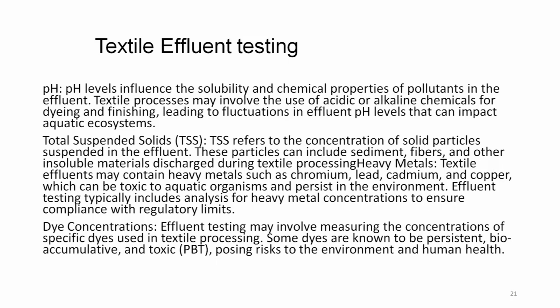pH levels influence the solubility and chemical properties of pollutants in the effluent. Textile processes may involve the use of acidic or alkaline chemicals for dyeing and finishing, leading to fluctuations in effluent pH levels that can impact the aquatic ecosystem. Total suspended solids, TSS, refers to the concentration of solid particles suspended in the effluent. These particles can include sediments, fibers and other insoluble materials discharged during the textile processing.